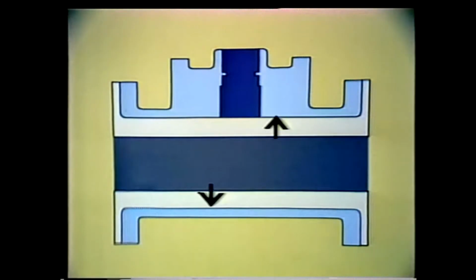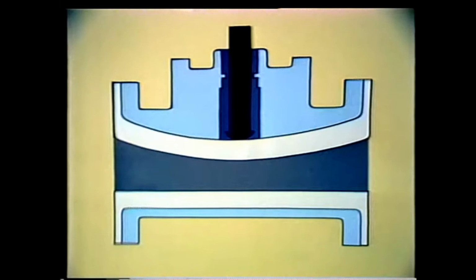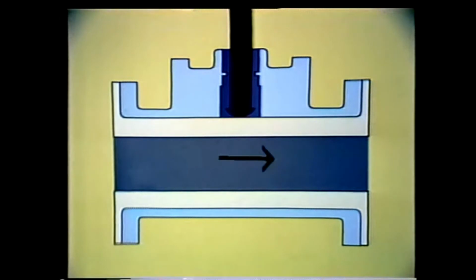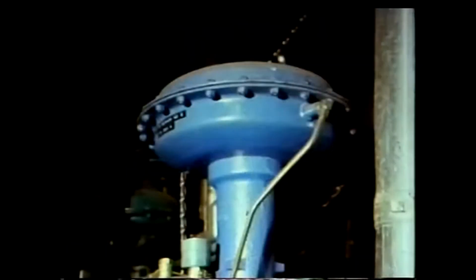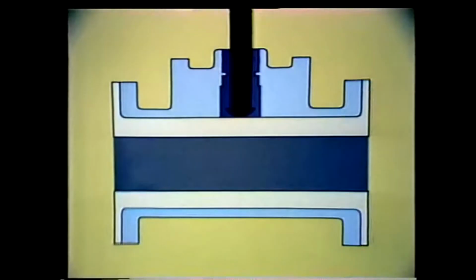The flexible tube serves as a protective barrier or sleeve to form a seal, preventing dirt or other contaminants from entering or leaving the system. A disc or compressor arrangement is used to shut the valve, quickly pinching off the flow. System pressure and flow then force the sleeve open as the stem and compressor are rotated to the open position as well. Now, the pinch valve can be operated manually or with a power operator.